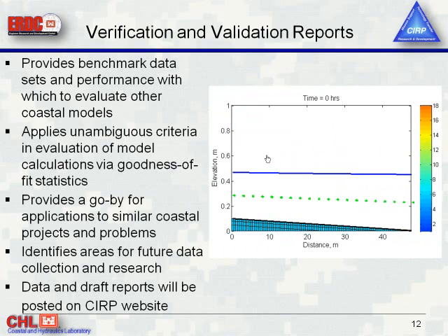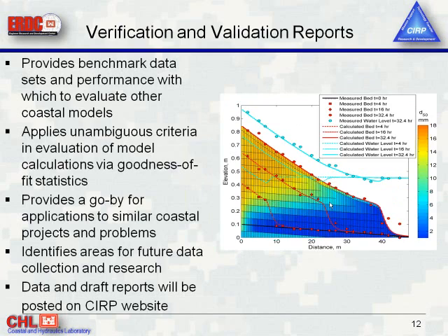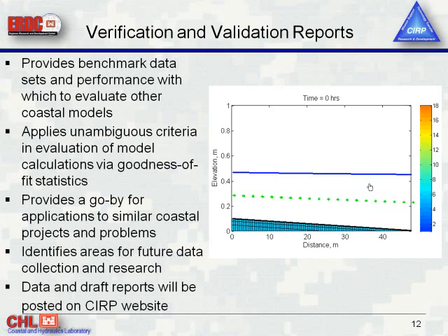So I'll show this animation because I really like it. It's the only animation I'm going to show today. You'll see how the sediment starts going in and how the little rectangles are bed layers, and the colors indicate the median grain size, the D50. So you can see how downstream it starts sorting out, and these lines and dots are the bed elevations at different time steps. The blue dots are our water surface elevation. So I'll just let it run.